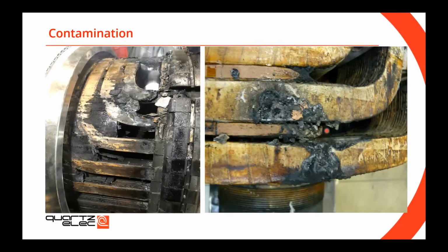Therefore, you have not only an interturn fault in the coil stack, but you have a fault and short circuit between two adjacent coils. That produces a lot of heat, and these two examples show you the consequence of the rotor having an air fault. So it could be that painful. For you to remember, air-cooled machines are very prone to that contamination, unlike, say, hydrogen-cooled machines. So air-cooled machines, guys, remember, replace these air filters because it's very, very important.